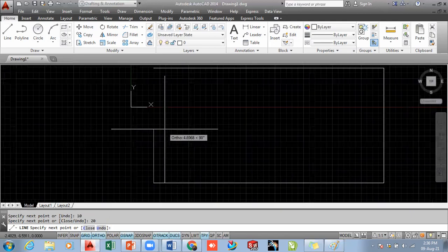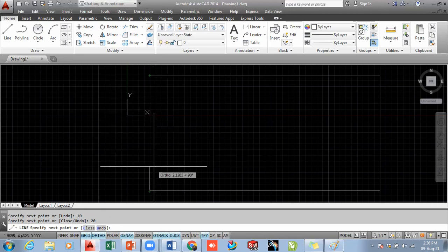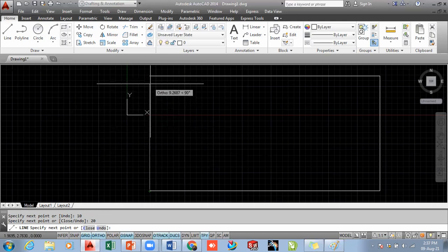Right. And now see, in the upper direction, again, you need to create a line. So what is the length from this point to this point? This is 10 mm. So in this step, we have different options to close this shape. You can just click the point directly here.